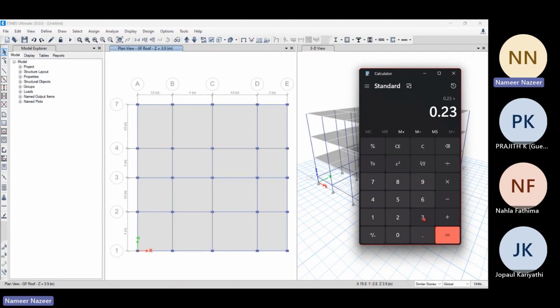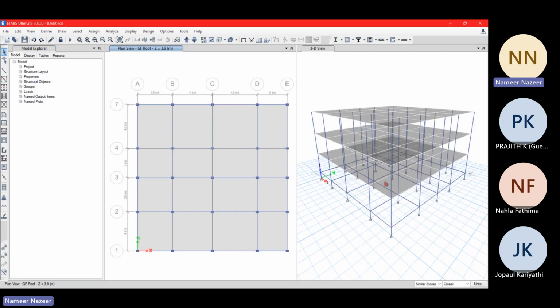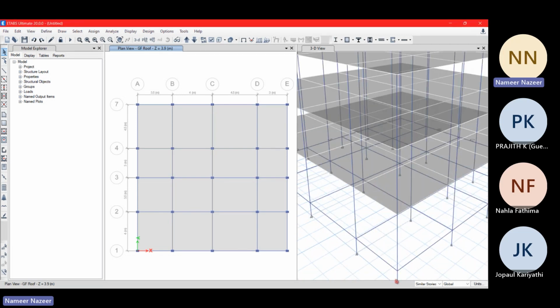It is because we have provided a beam, right? What was the beam depth we have provided? We have provided a 250 mm beam depth. So the beam will be in that portion, right? If I select the structure, see this plinth level, if the beam is over here, this is the total 3 meter height, up to this grid. So the story height will be different.